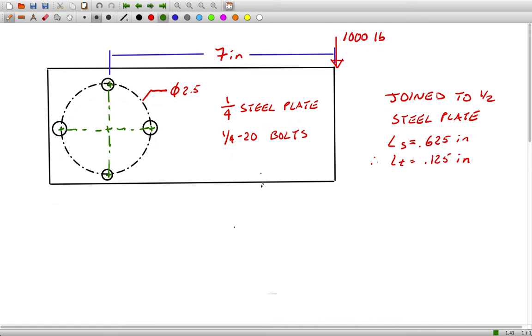Alright, this is the first in, I guess, 3 quick videos that just talk about calculations of bolt forces in particular. The only ways that you can really generate stress in a typical bolted joint is either direct shear stress or tension. Tension can be due to the preload on the bolt. It can be due to an external force. It can be due to both. The shear is pretty well always due to some external force.